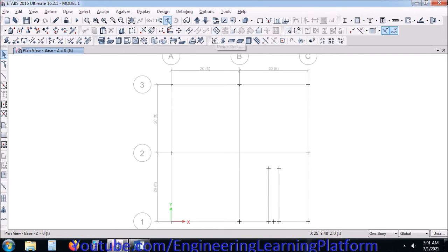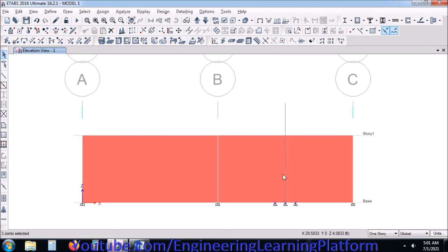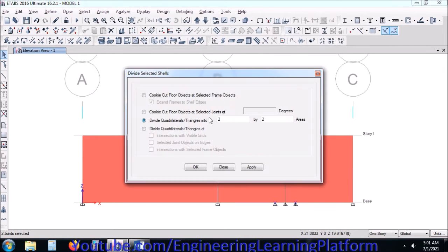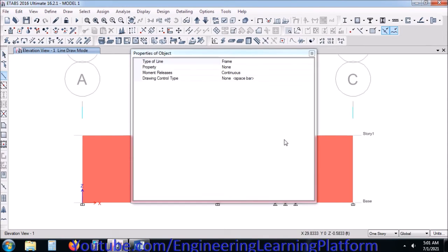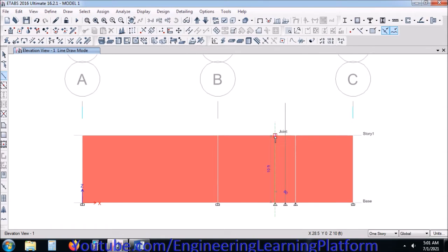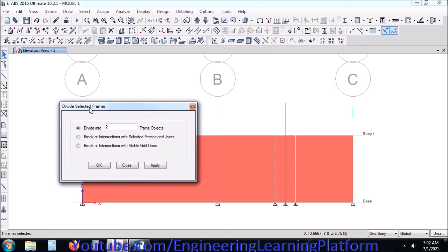So I am creating a doorway in the wall. Since the wall height is 10 feet and I need a 2 feet masonry over the lintel of the opening, I'll divide the model line into 5 segments, so that 10 feet becomes 5 segments of 2 feet.